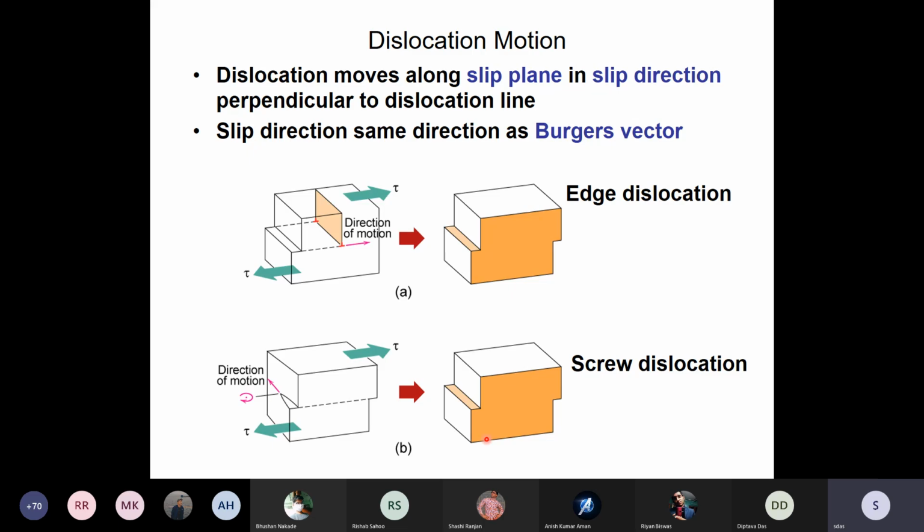It doesn't have a densely packed plane. So even though it has 48 slip systems, none of them is as effective as any slip plane of face-centered cubic or hexagonal close pack. So BCC is not ductile.